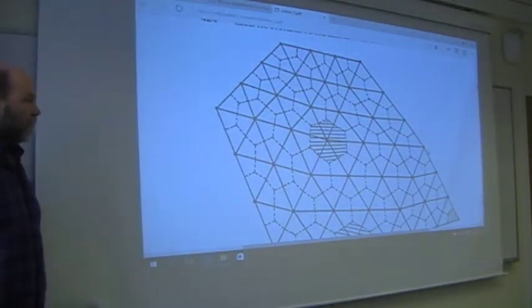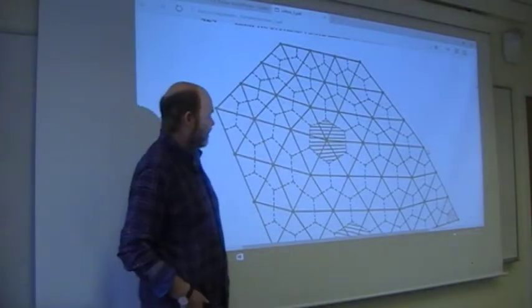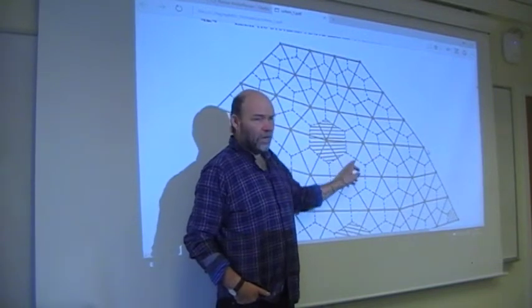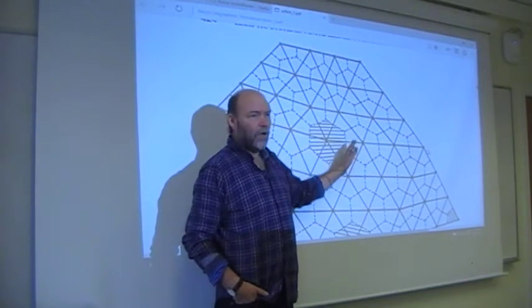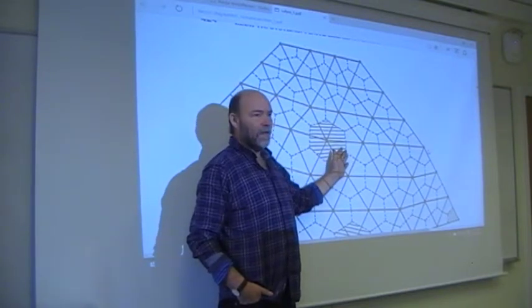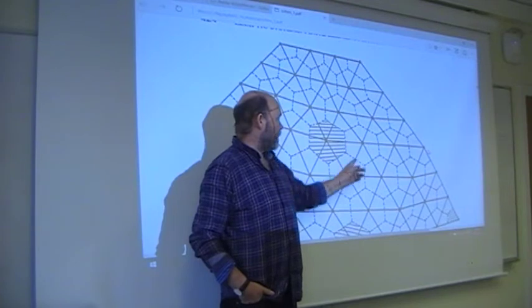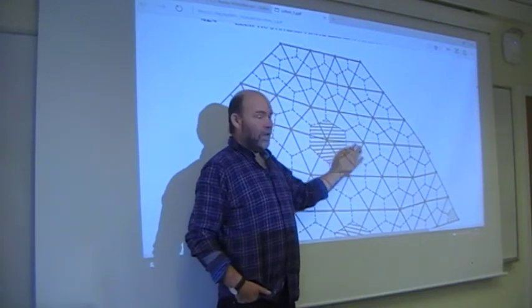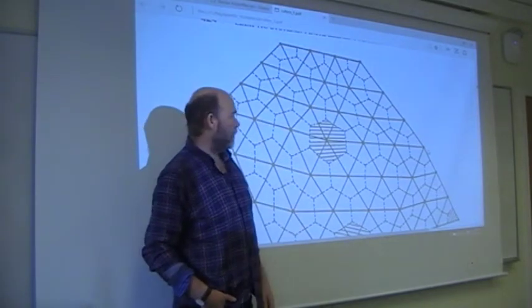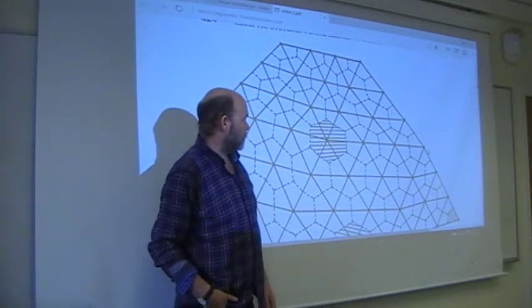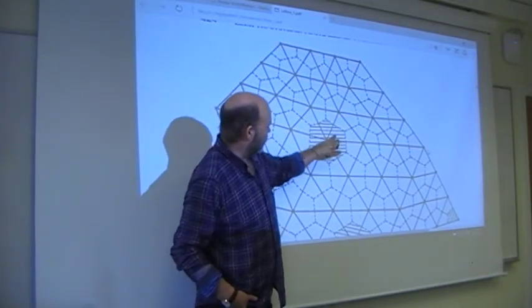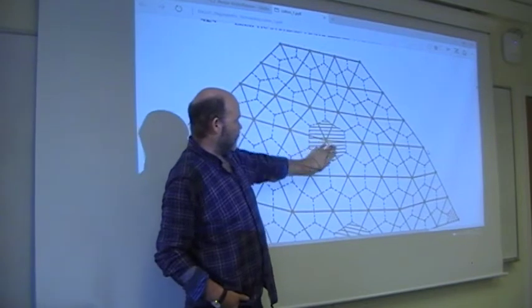The reason here that I call it finite volume is that within one triangle you have then 3 unknowns, and the only variation allowed in this context here is linear variation, meaning inside one triangle you can only have, say, a flat plane of your unknown. It can only vary as a linear function. Of course, in this volume then you could have several different angles of this solution plane.